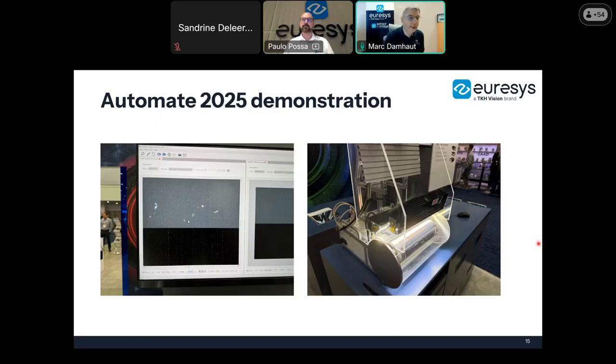So we end up on the top of the image here with the bright field illuminated image, and at the bottom of the window, the dark field illuminated image. And this is all done by the frame grabber during the acquisition, using DMA, what we call DMA de-Interlacing or DMA de-Interleaving.